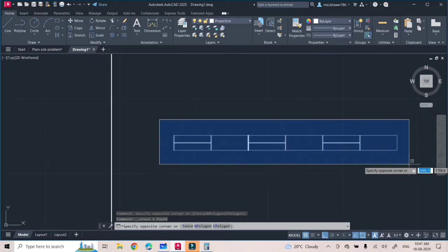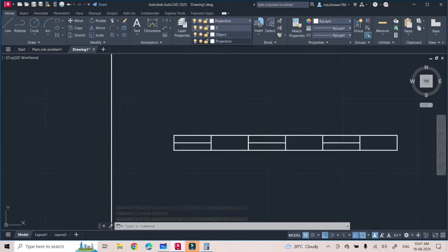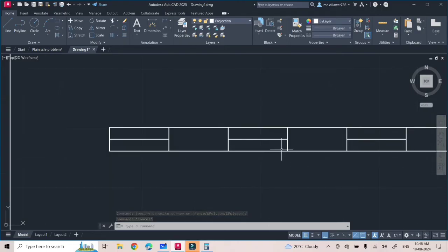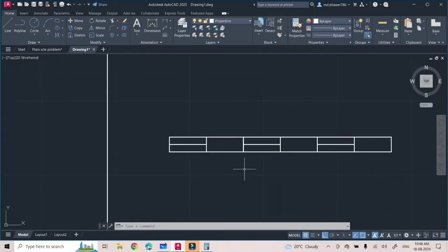Next, this outline, this object of your scale must be highlighted. That means thick lines, but not too thick. Better to take 0.3 or 0.35 mm only, right? Now you have successfully drawn the scale. So we need to give labeling.